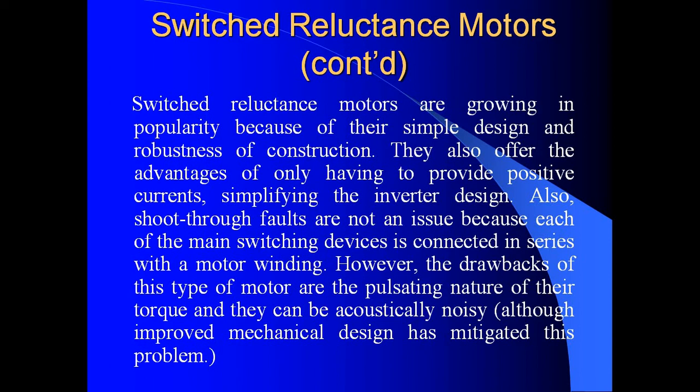Also, shoot-through faults are not an issue because each of the main switching devices is connected in series with a motor winding. However, the drawbacks of this type of motor are the pulsating nature of their torque, and they can produce oscillatory noise, although improved mechanical design has mitigated this problem.